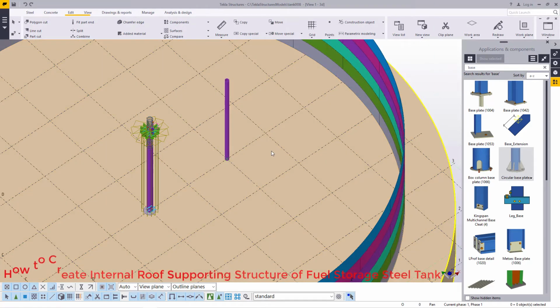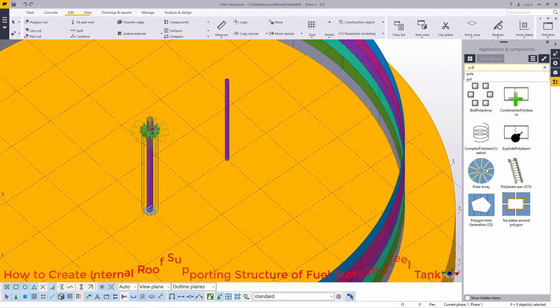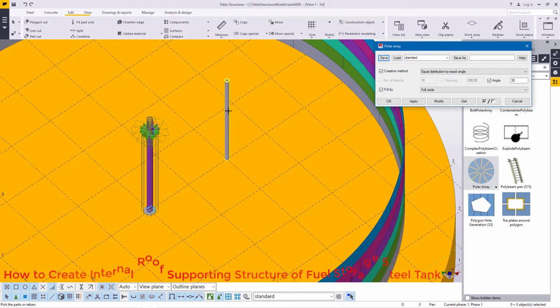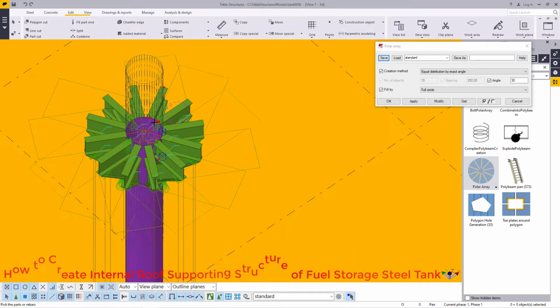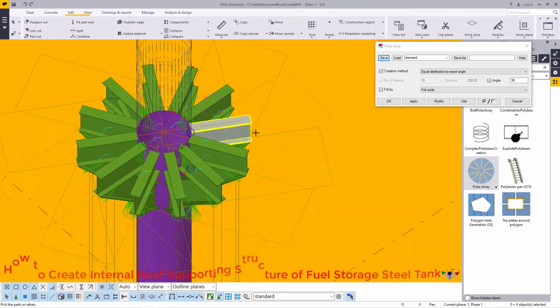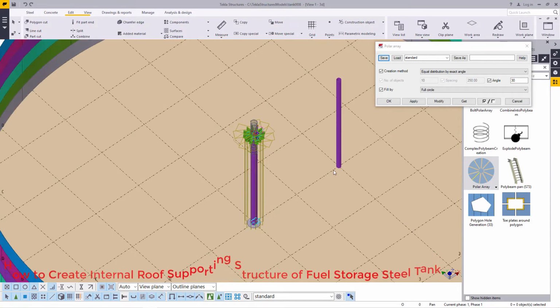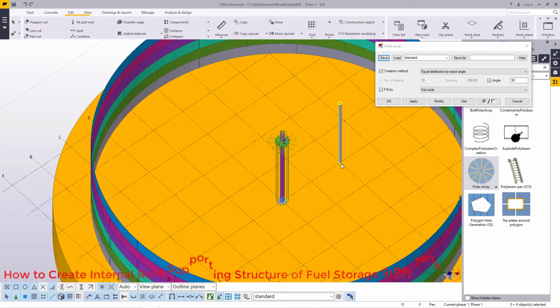So in this particular case, what I'm going to do is just follow the same process. I'll select on this. Once I've invoked that command, polar, just type polar, and I'll double click on it, and I'll pick on the component I want to create. So once I've done so, on the same location, I'll try to put a point here just to mark the points.